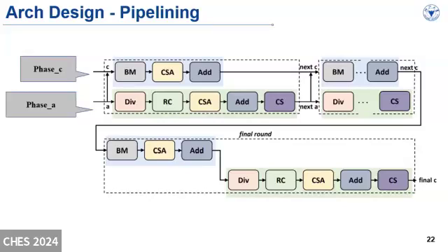The pipeline implementation of the engine has 5 stages for each iteration. Each stage takes 4 execution cycles. Since phase A has a longer data path than phase C, we divided the data path into 5 parts. The pipelining strategy used in our Shaper architecture significantly improved the throughput of our designed engines.